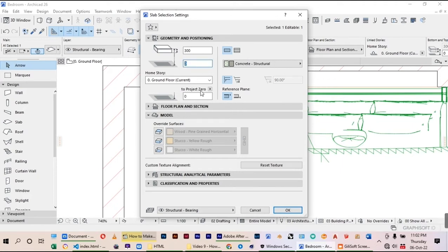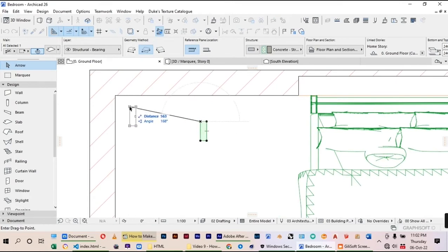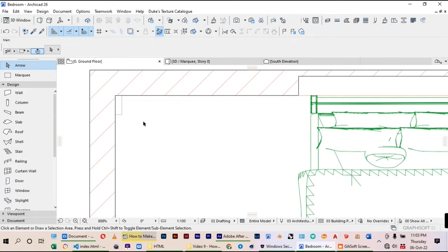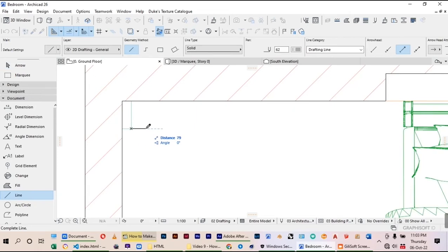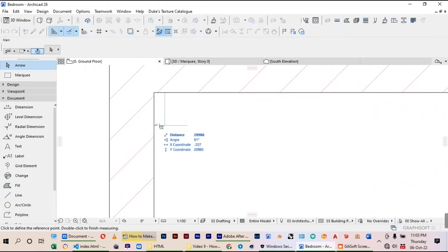Use this one. We're talking of a height of 2400 and 2400. Enter. And then you can align them here. Let's do the first one against that wall. And then we determine how many of these do we need here with the spacing. I need to space each by at least 100. So the question that we need to ask ourselves, what is the length of the strut and the space?